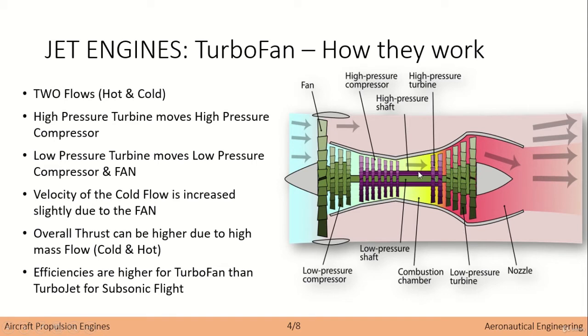as a reminder, you know that the pressure at this point is relatively low, then it increases and it continues to increase. So this is why this is the high pressure compressor, and this is why this is the low pressure compressor, okay, because the flow at this point is at lower pressure conditions. Now, as I was mentioning, that low pressure turbine, so this part over here, the exterior part, okay, will actually move the low pressure compressor and also the fan.